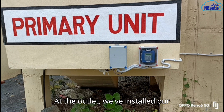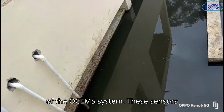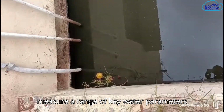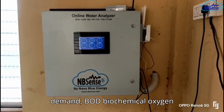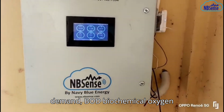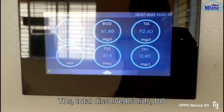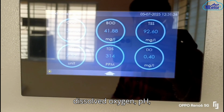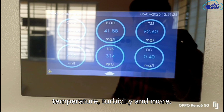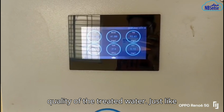At the outlet, we've installed our advanced water quality sensors, also part of the OCEMS system. These sensors measure a range of key water parameters, including COD (chemical oxygen demand), BOD (biochemical oxygen demand), TSS (total suspended solids), TDS (total dissolved solids), DO (dissolved oxygen), pH, temperature, turbidity and more. These values help assess the overall quality of the treated water.